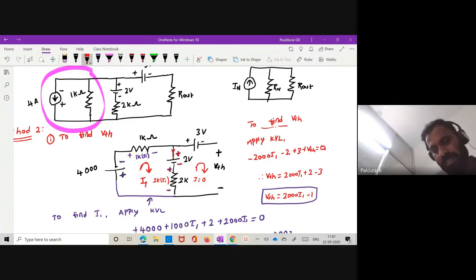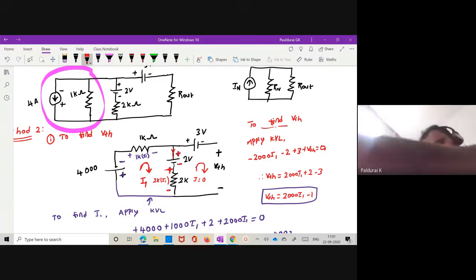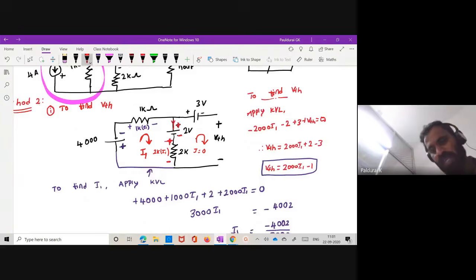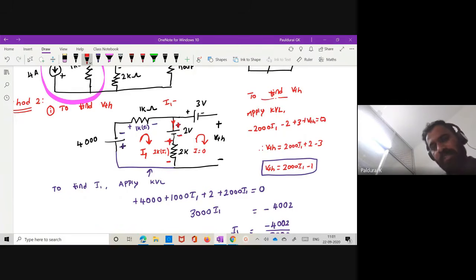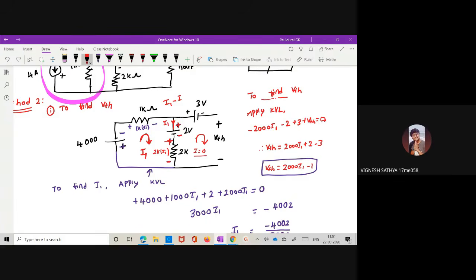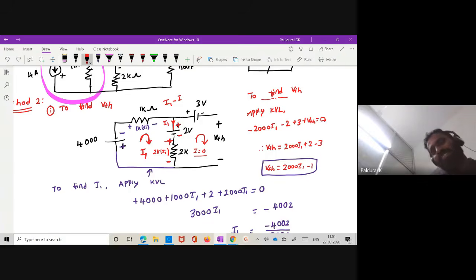So this is a voltage source plus minus, but here for a resistor we always choose current entering as positive. Are you taking the current as I1, or which loop? Actually this is an open circuit, sir, the right side is open, so here I take I0, here I take I as 0. Okay, but what is the current flowing here? The current here is I1 minus this current I. Since I took it as 0, only I1 will flow. Hence this current is 0. How are you taking the direction, sir? The direction is as usual clockwise. Okay, clockwise. So in clockwise, the current flowing here is I1 minus I2. Similarly, take this current as I2, no problem. But I2 is 0. Okay, what is the current flowing here? I1 minus I2, where I2 equals 0, so obviously I1 alone will flow.